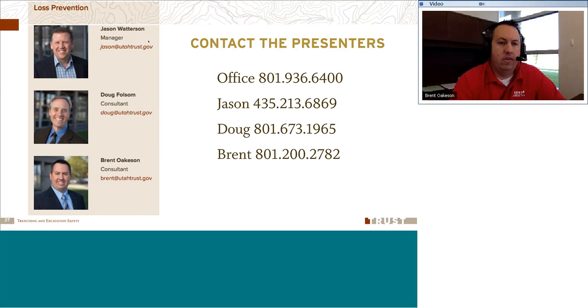Yeah, where this is a safety moment webinar, we don't dive into the preventative maintenance quite as much, but that's one of the things that, as I've been through my career, I've seen some fairly serious things happen. Just that simple preventative maintenance of actually inspecting your circuits, particularly the big stuff, and a part of your PM program should definitely be thermal imaging. Those cameras used to be very expensive. Now you can pick one up that will plug into your phone, and you use your phone as the display, but you can have thermal imaging that we can see if there's a problem with our system from feet away, and determine where our maintenance priority should be. So that's just something that kind of popped into my head.